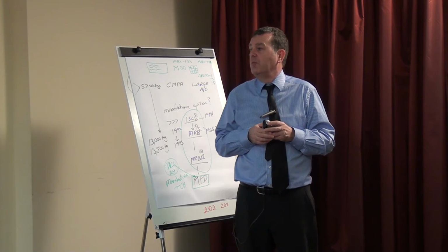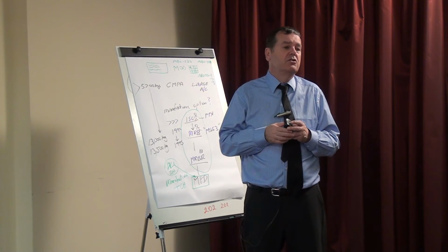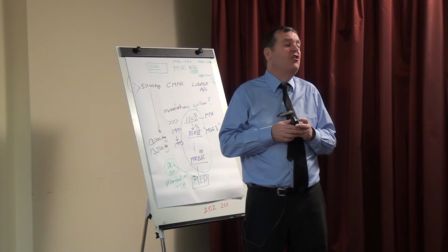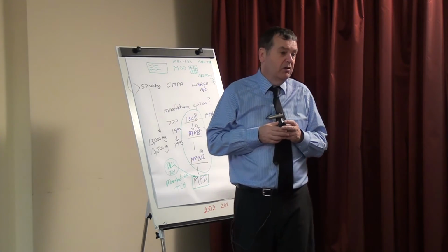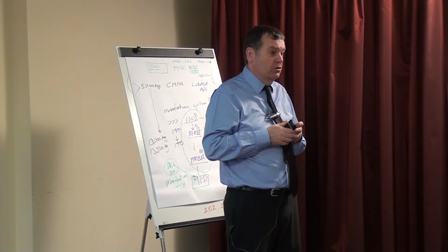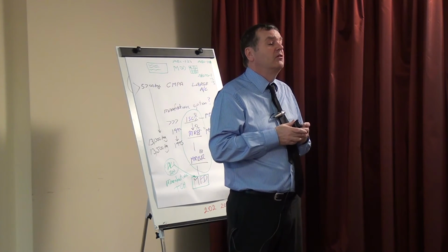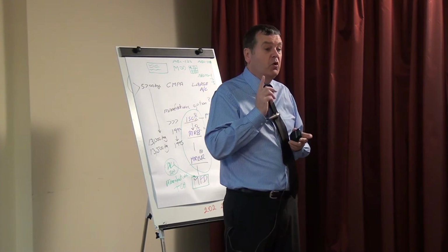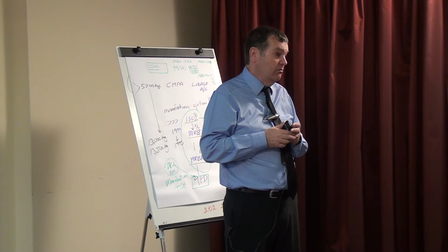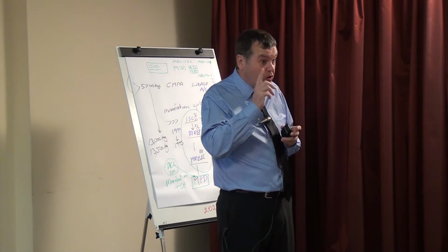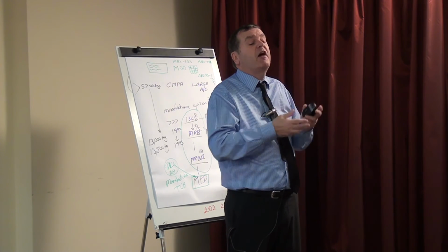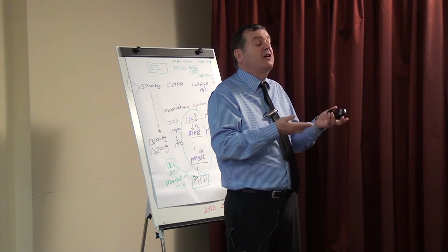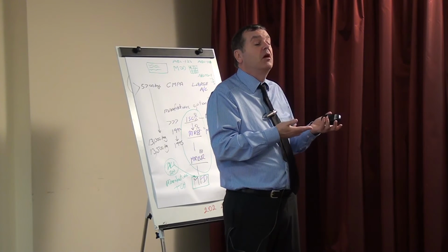Over a time, a number of drawbacks were found using the MSG2 process. MSG2 was not designed to consider economic effects. What does that mean? Well, we would let something wear out when we could have kept it longer by looking after it in a different way. Remember, we said the most important task we can do on an aircraft is lubrication. So if we don't lubricate something that we could have lubricated, because we said, well, if it fails, it doesn't matter, eventually it is going to fail, and because it wasn't lubricated, it's worn and we can't do anything with it.